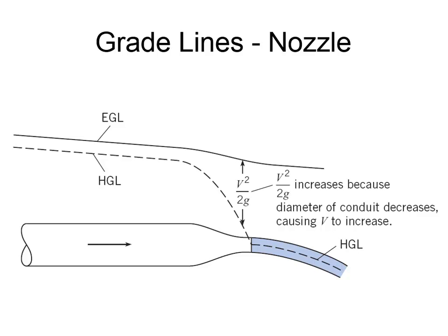Well, kind of, but let's not look at the fact that it's jetting out. Before the jet, why is the pressure decreasing? It's the Bernoulli effect, because if the velocity goes up, the pressure has to go down. So what we're seeing is the manifestation of Bernoulli's effect. That's the same thing that we saw in the Venturi experiment, that there was a big drop in the piezometer.